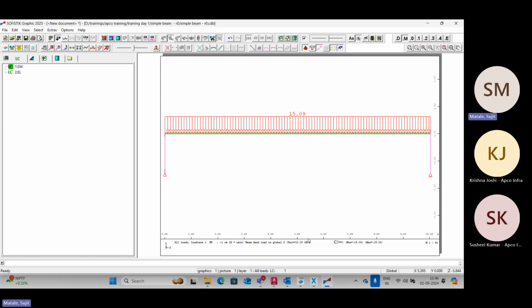Now, why I'm stating this is because whenever you are going for any checking and all, okay, I want to verify what my cross section area is, then I can simply go have a look at this number divided by my unit weight and come back to my cross section area.